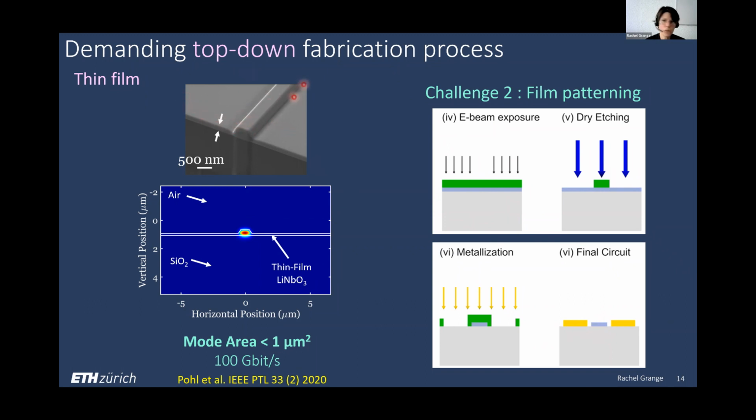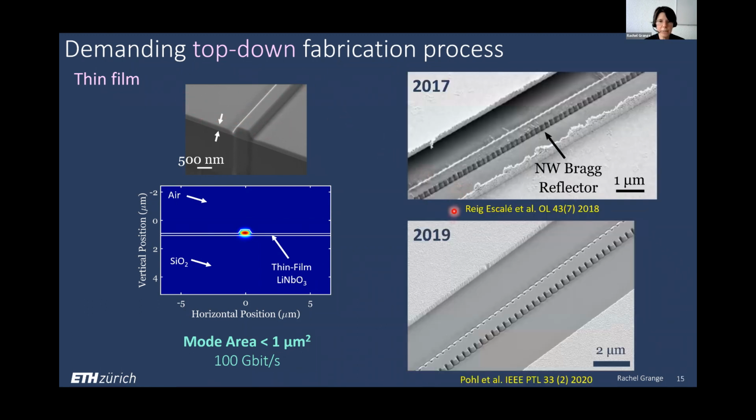Here you don't see the electrode, you just see the waveguides. But on the next slide, here you have our early fabrication steps, where the electrodes were a bit detached and the walls were not so smooth. Here you see a nano waveguide with some features that can be used as gratings, so Bragg gratings along the waveguides. And here you see the striking improvement of the fabrication over the years, where the gold is not so smooth because it is sputtered, but the lithium niobate is very smooth. This is done by ICP etching and e-beam, so you can see you have a Bragg grating.